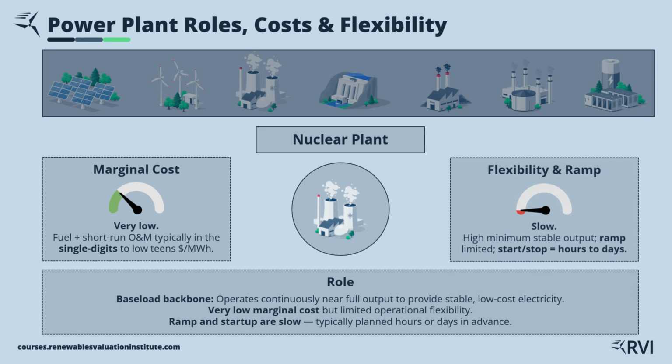The trade-off is flexibility. Nuclear plants have a high minimum stable output. They ramp slowly, and starting or stopping them can take many hours to days. So operators plan changes well ahead. Nuclear is not what you use for quick peaks.